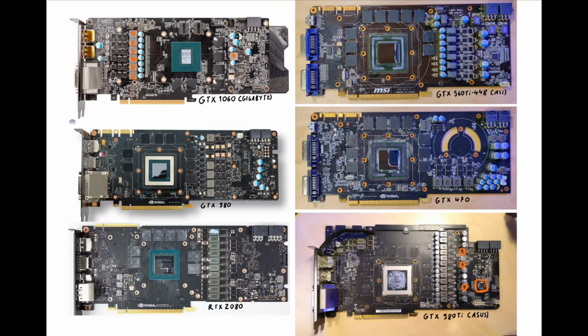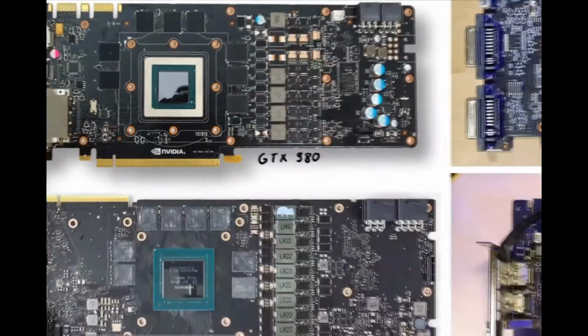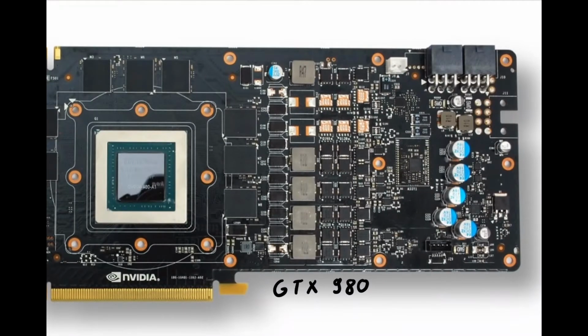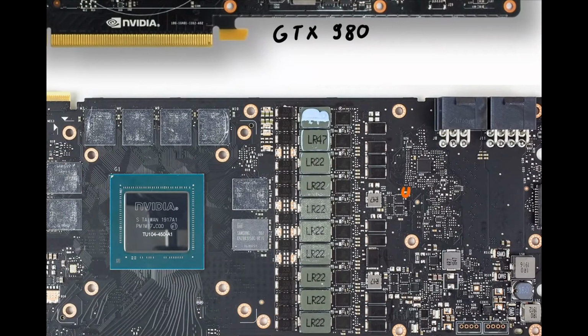And in that datasheet, it will tell you how many PWM signals that PWM controller can put out or does support. So in case of the NCP4208, it would be 8 PWM signals. Or for the UP9512, it would also be 8 PWM signals.